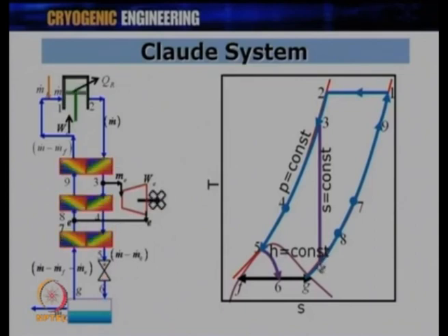So, as a result, as you can see, the heat exchanger output is actually at T7, while the expansion engine output is TE. Combining both these, the point at the entry of this second heat exchanger is at point 8. This is because of the cold which is generated during the expansion 3 to E. I hope this is clear.